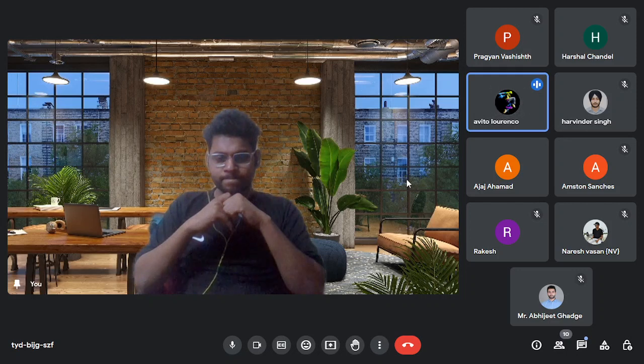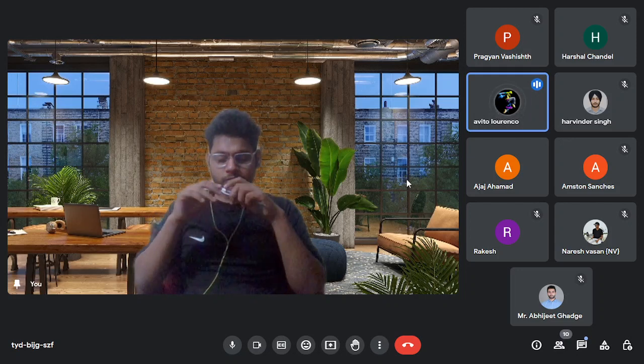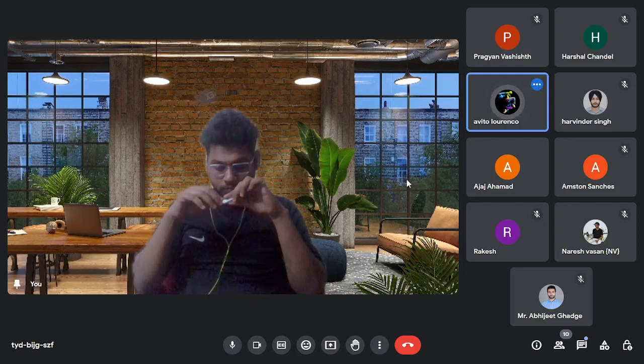If this 30 bar air, from the second stage of compression, goes into the water, we know water is incompressible. So it will pressurize the whole water also to 30 bars, because the pressurized air keeps trying to come out. The 30 bar water could then damage the entire walls of the intercooler or aftercooler. That is why the bursting disc activates and saves the rest of the enclosure by allowing the water to drain out.